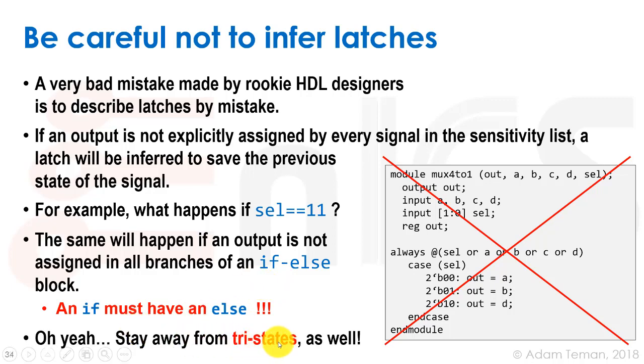And stay away from tri-states. Don't assign a z. Digital designers don't like it. In some places you will use them, but that's in very specific places where you really know what you're doing and your company decided that that's what you have to do.